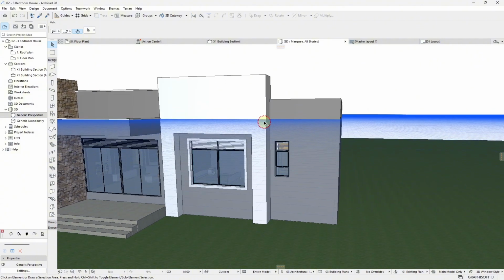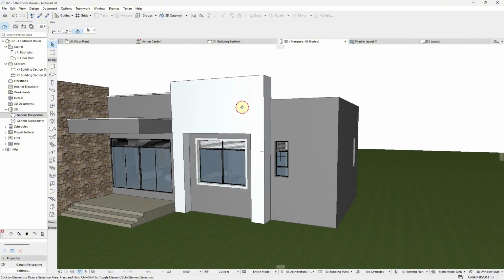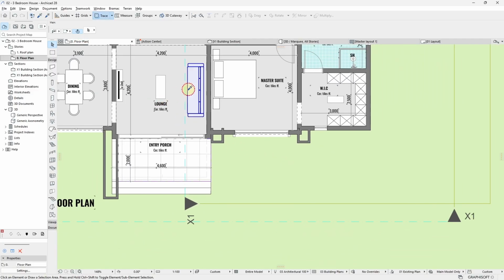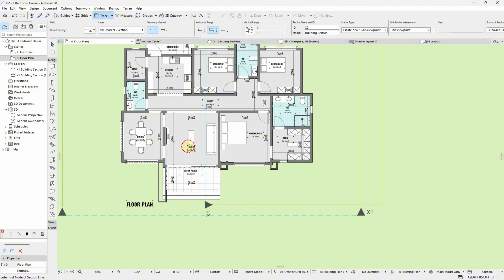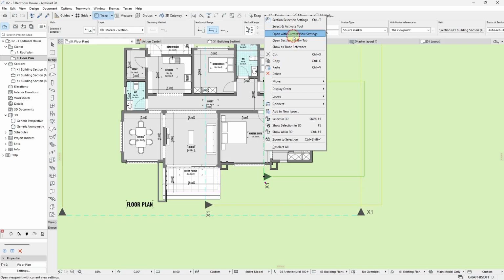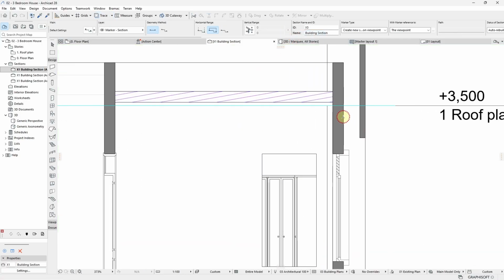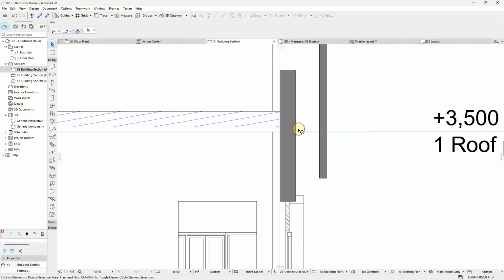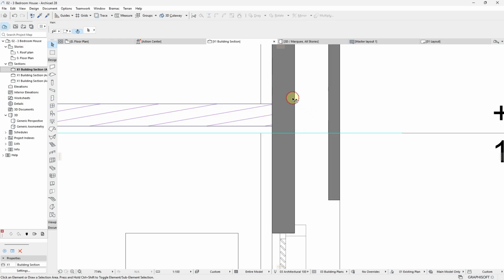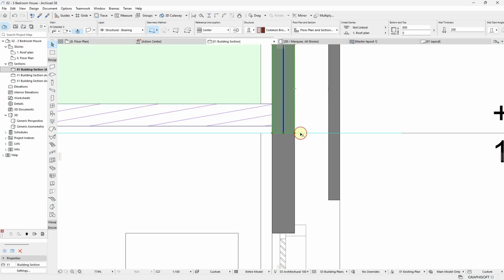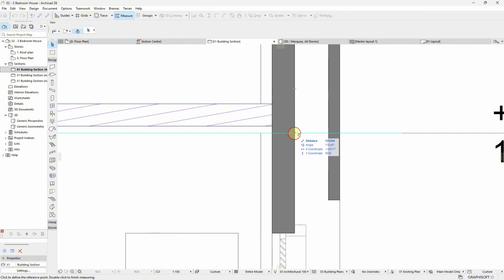Okay, so I'm going to do something like this at this particular spot on the building, but this won't be as high as that. So I'm going to come in my section and I want to see where my roof is. So I'm going to cut a section here and I see through. So my roof level is kind of high here. So that means I realize that my roof is draining at this level here. So that means the down pipes are going to start from this level here, the valley.